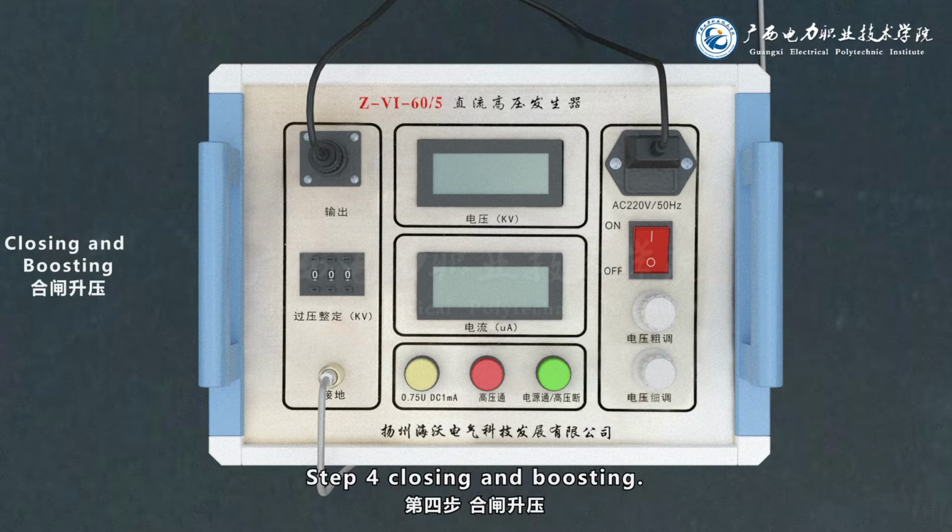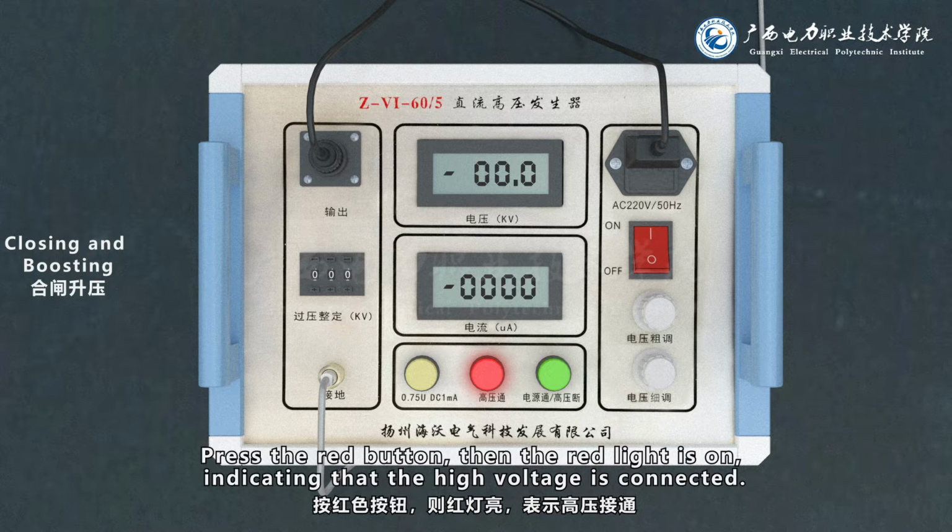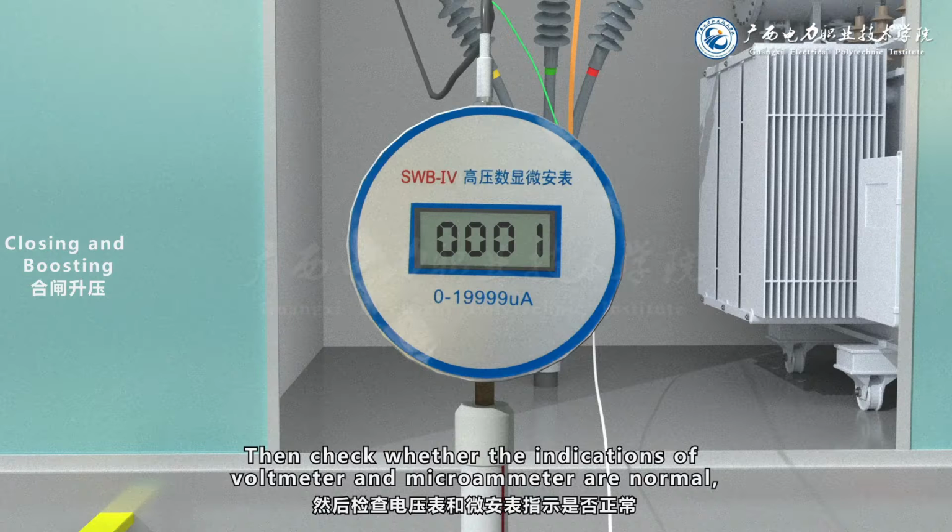Step 4. Closing and boosting. Turn on the power switch. The green light is on at this time, indicating that the power is on. Press the red button, then the red light is on, indicating that the high voltage is connected. Then check whether the indications of voltmeter and microammeter are normal.